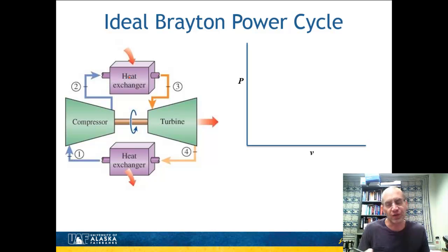And then we go into a heat exchanger. This is essentially just a large burner, and often they're gas-fired burners or oil-fired burners, depending on what the cheapest fuel is at the time. It heats the gas up, and usually this occurs at more or less constant pressure, and the ideal Brayton cycle will assume there's no pressure drop. And then we'll take this hot gas that is pressurized, run it through a turbine to generate some work, and then it will exhaust. Now, if this is just an air mixture, often this is just exhausted into the atmosphere, and then we bring in new atmospheric air. We can kind of simulate that as a heat exchanger.